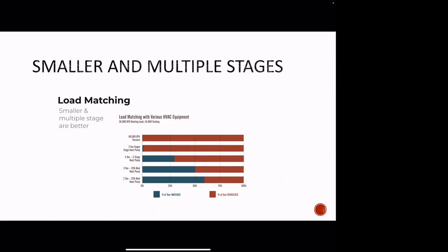Not very. 3%, 2% of a winter? How often is it 95 degrees outside, 92 degrees outside? 10%, 8%? So we're saying that it's oversized 90 to 97% of the time. That's going to be comfort problems. So understanding the home, multi-stage equipment, better commissioning, better setup is going to allow us to actually control it better and have a happier client and a more comfortable client or homeowner.